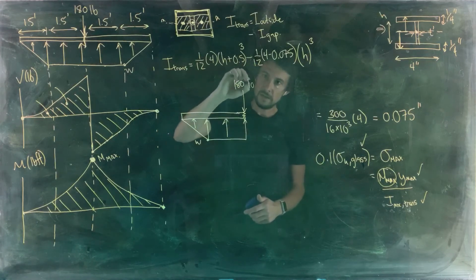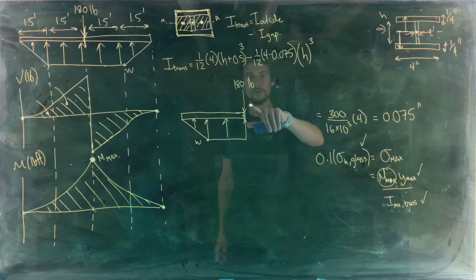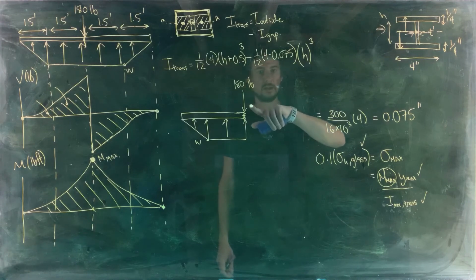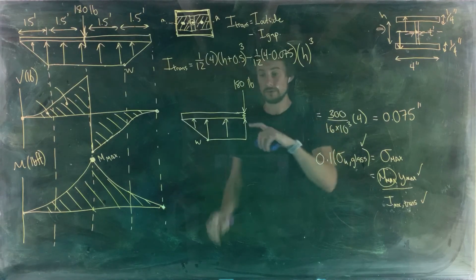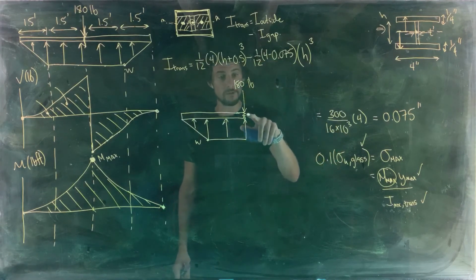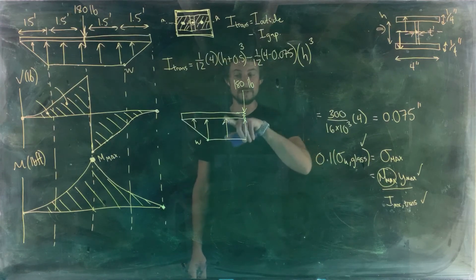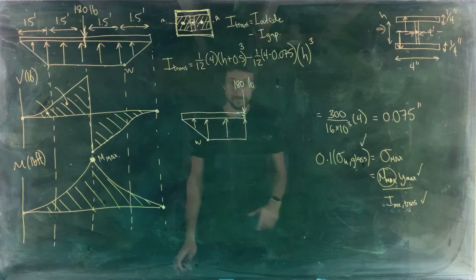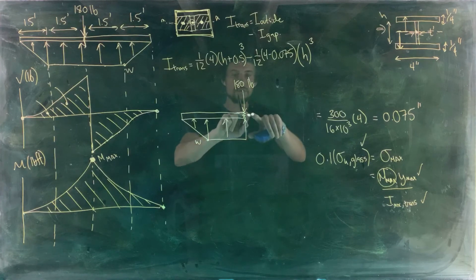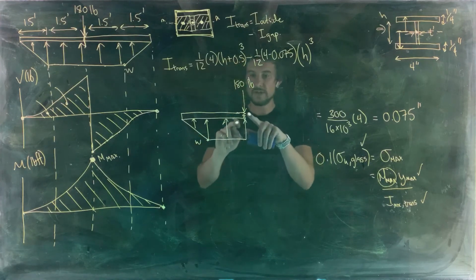The answer about whether you include it or not is that it doesn't make a difference what your choice is. It's going to affect the internal shear present, but it's not going to affect the internal moment. So in terms of internal forces here, we've just done a section cut.